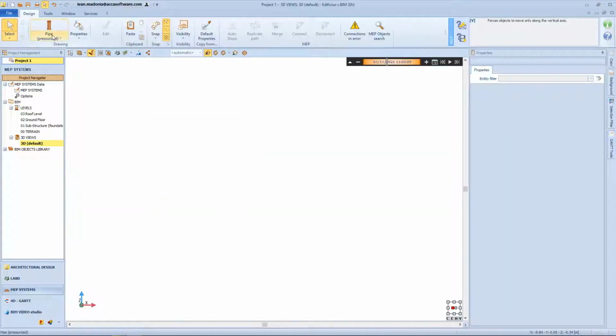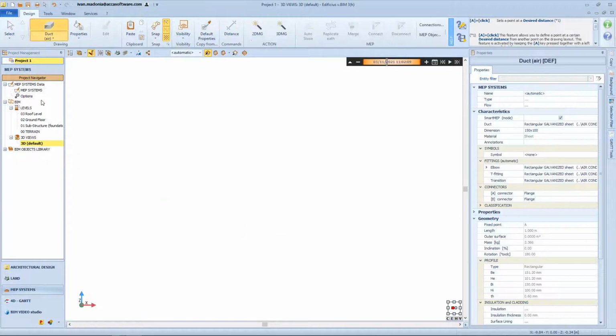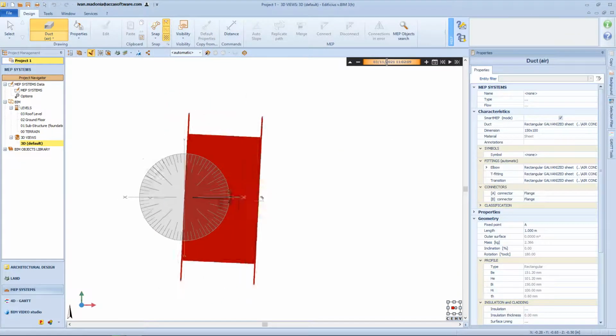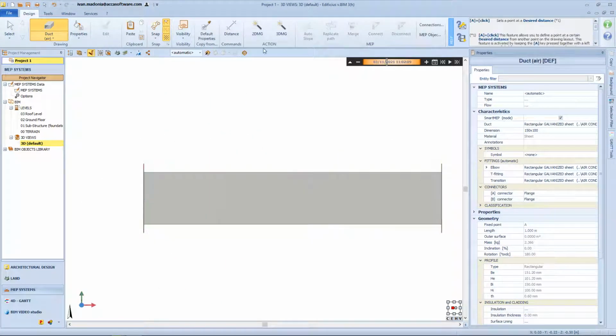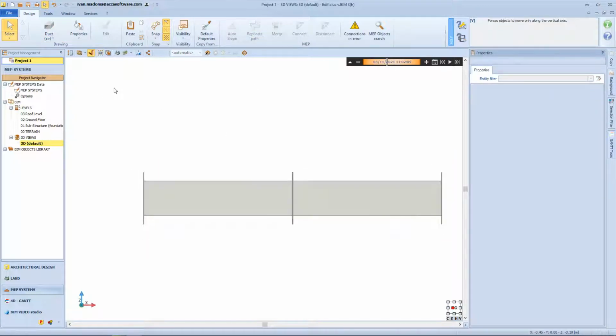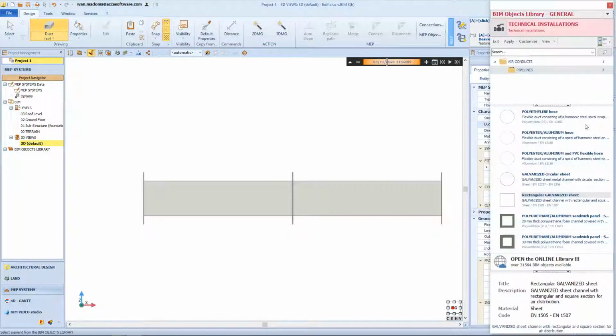If you choose a rectangular duct, all the default fittings have rectangular profiles. If instead it is set to a circular shape, all fittings by default will be set to circular profiles. If the main pipe has a rectangular profile and you need to derive a circular section pipe, simply change the automatic T-fitting on the branch pipe. After initially modeling the main pipe with a rectangular shape, change the profile for the branch pipe, choosing the circular one from the library.